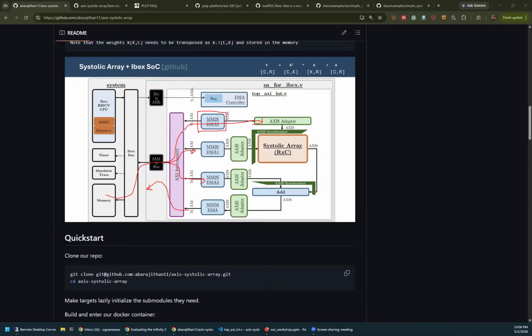One of the key factors about performance is this configuration port, and the configuration port is an AXI-Lite port. You give your configuration there, and the DMA starts fetching data, and before it even finishes fetching, it takes the next configuration, right? So that way it's very performant.